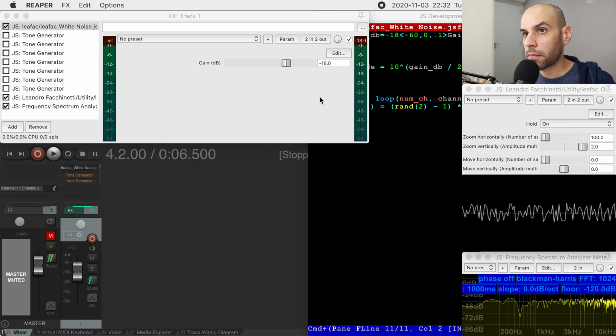Ideally, you would play something like white noise because it has energy across the spectrum. So it has energy that is low in frequency, and in that case, the speaker cone is moving more slowly. But it also has energy that is higher in pitch, so the speaker cone is moving more rapidly, it's moving faster. And if you add everything together, you are exercising the whole material your speakers are made of.